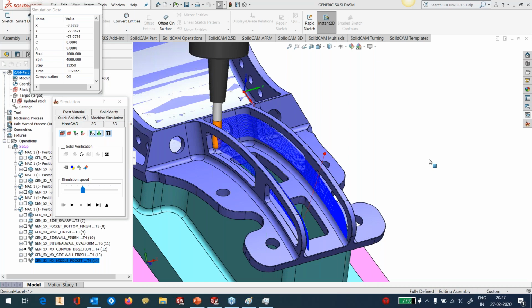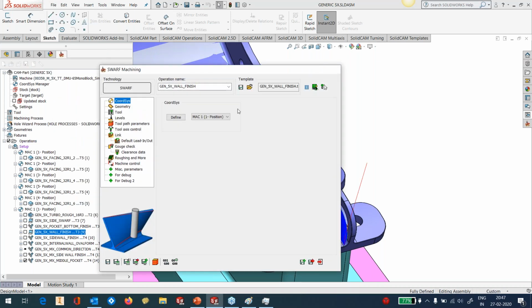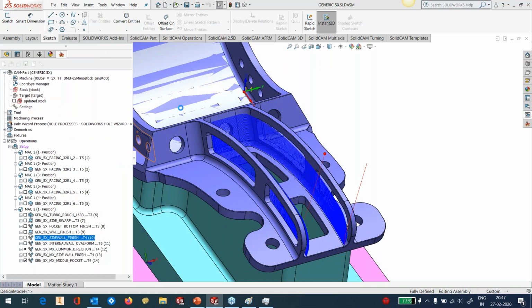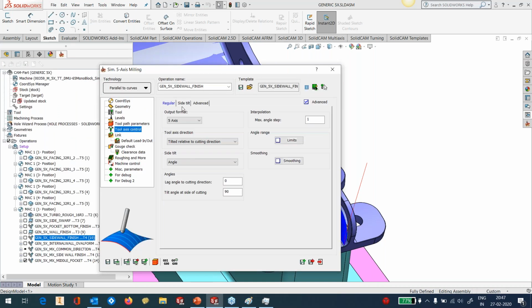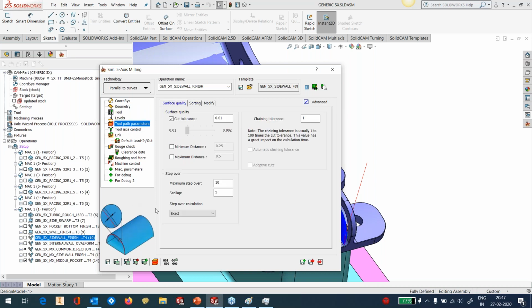If there are no more, there's another question on how to use tool compensation for swarf milling. At the moment, we do not have tool compensation for swarf milling. In the event that you would like to use a swarfing kind of technology, then I would suggest you go back to our generic machining. So if I go into, not this one, sorry, on the swarf. If I go into the generic technology, where is it?